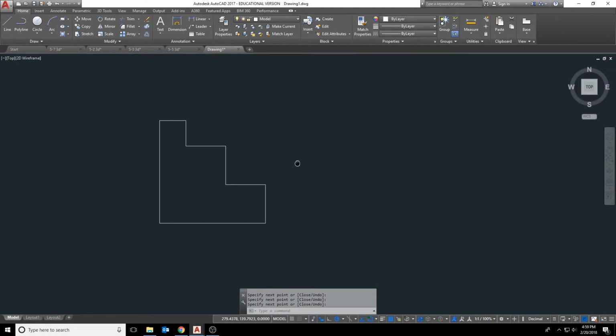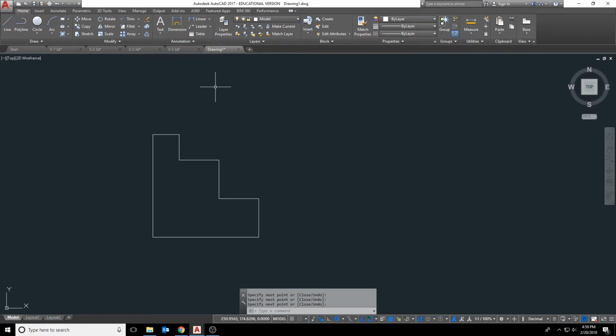So now I can begin to draw my right side view and my top view. The view spacing between the views for anything that deals with metric is going to be 25 millimeters. If it was in inches, we would be using 1 inch in between views. But since this is metric, it's going to be 25 millimeters. And there's some easy ways that you can start this. For example, when I do my right side view, I know that I want to just start with the box that's 40 by 40. So if I click on rectangle and then hover over this endpoint and move to the right, I can just type 25, enter, and it will start at 25 millimeters to the right. Now I can type 40, 40 to get the overall size of my box.